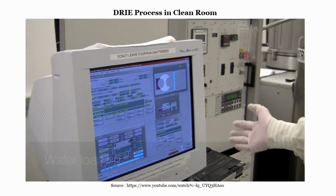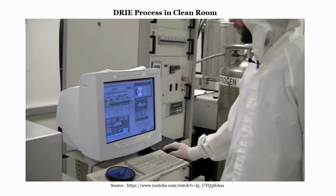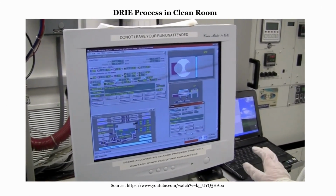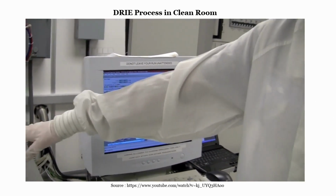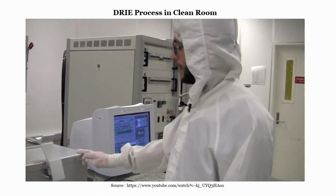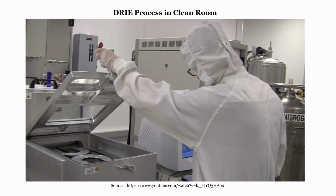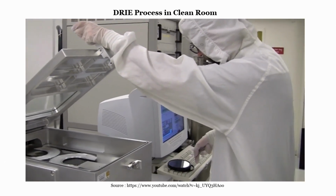Now the first thing to do is to load the desired wafer into the load lock chamber. We do that by going to the transfer window and pressing Vent. Once we press Vent, we have to wait for the load lock chamber to reach atmospheric pressure. Once the transfer chamber is under atmospheric pressure, we open it, and we will load the desired wafer into the chamber.